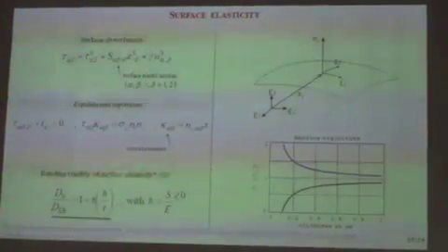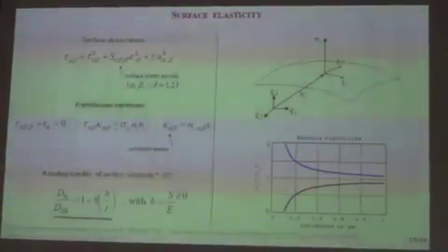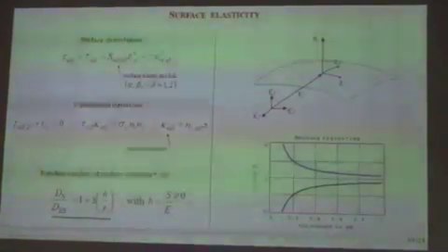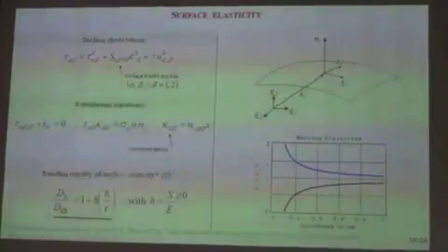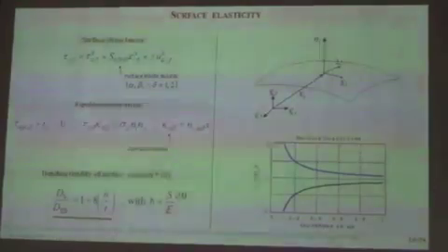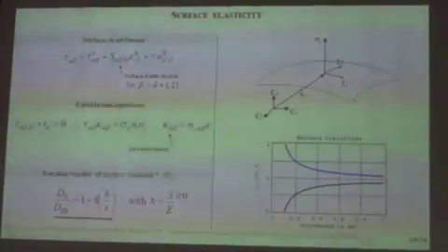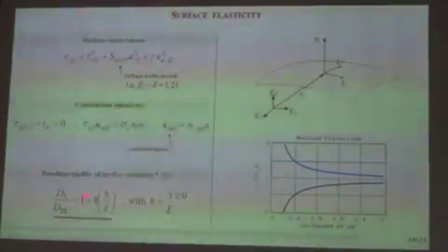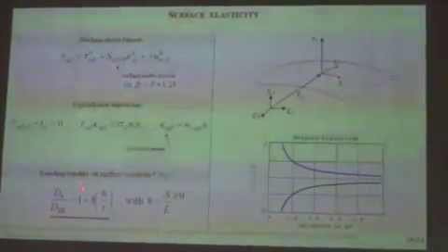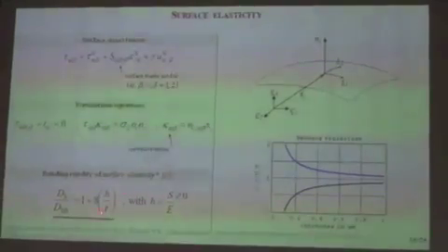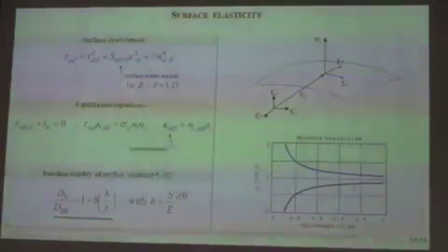And by doing so, I found in literature also a derivation for the bending rigidity when you propose the surface elasticity just as an enhancement of the conventional continuum theory. So here are no higher gradients, nothing else but conventional continuum plus surface elasticity. And there we can also derive formulas for beam bending and beam rigidities. And I compared them to Euler-Bernoulli, and I get nearly the same dependency on the thickness, but it's now not square dependency.